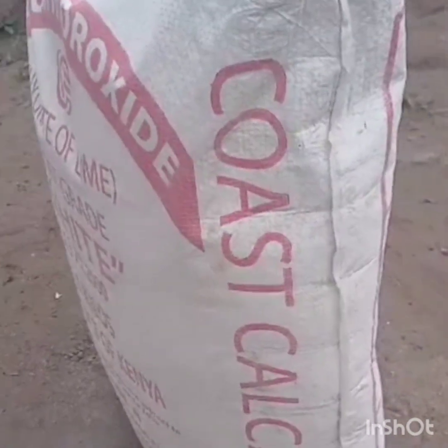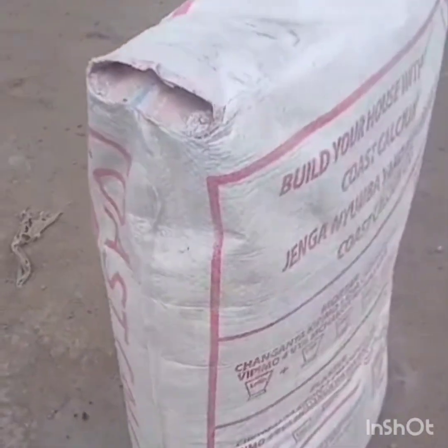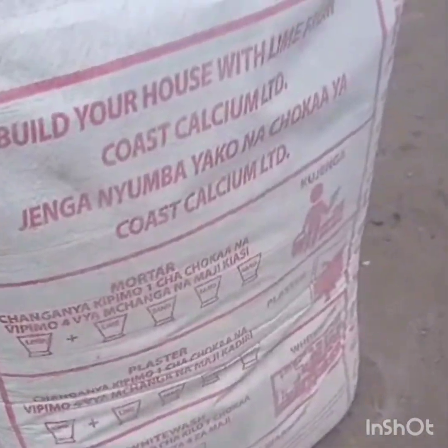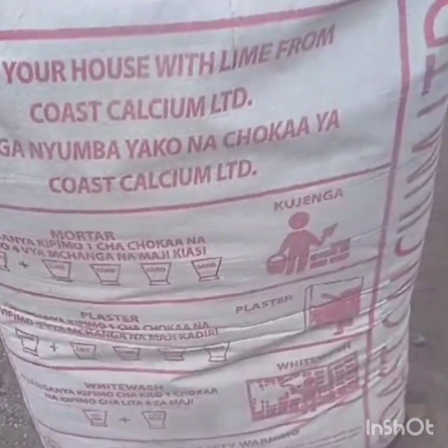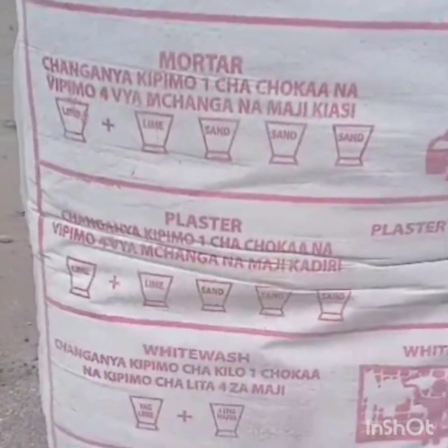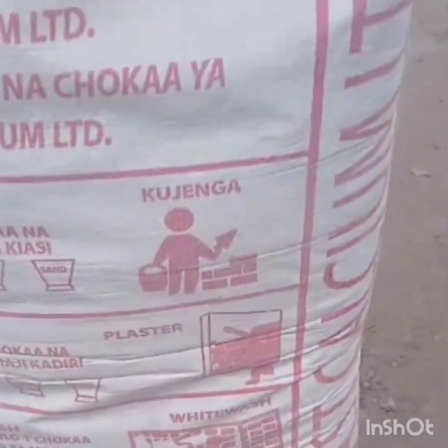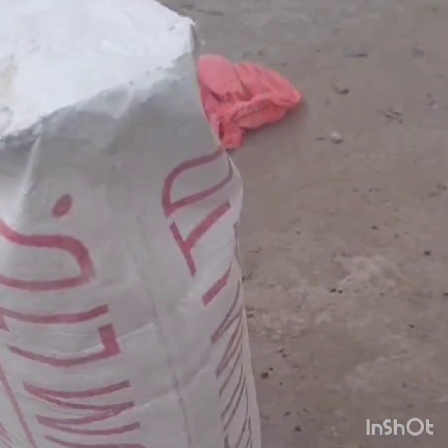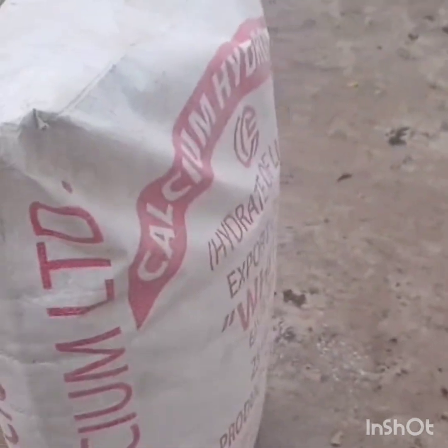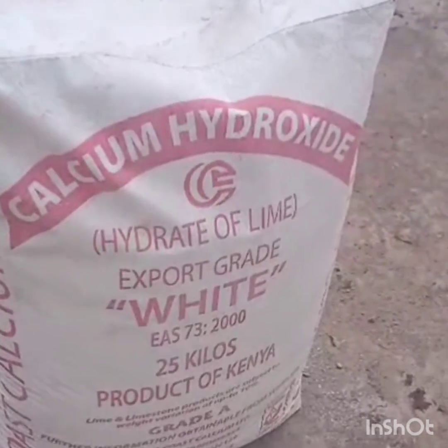So there are some ions in the lime that mix with the iron in the mud, and then they stabilize the soil. So after placing the cement and the lime, they of course tear the bags, then spread the sand, then spread the cement and the lime using the grader, then they mix it completely, then they ram it. So why am I telling this story?